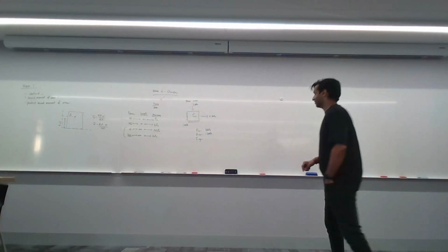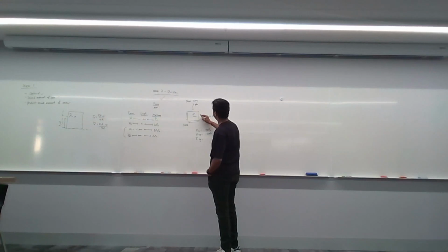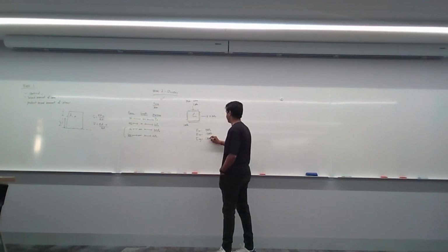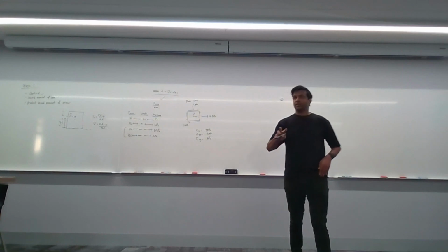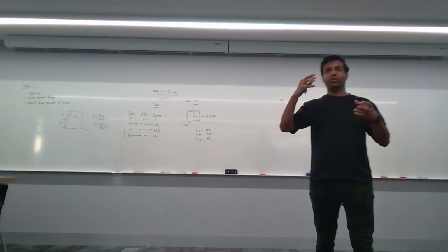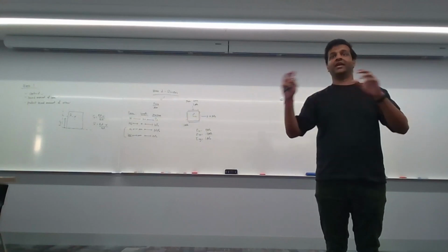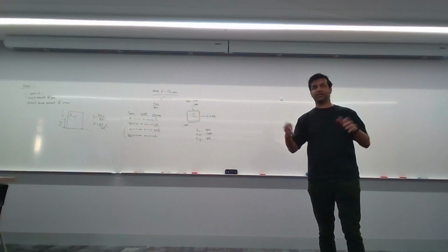Positive. Okay. So if you were to complete the arrows like that, on this side it'll be going this way, and on this side it's going this way, so that is positive 1 MPa. Does everyone see that? Right? You have to sort of memorize what the directions are for a positive shear, or what the directions are for a negative shear. Okay, and it's really important because it'll change your sign convention in your numbers completely if you